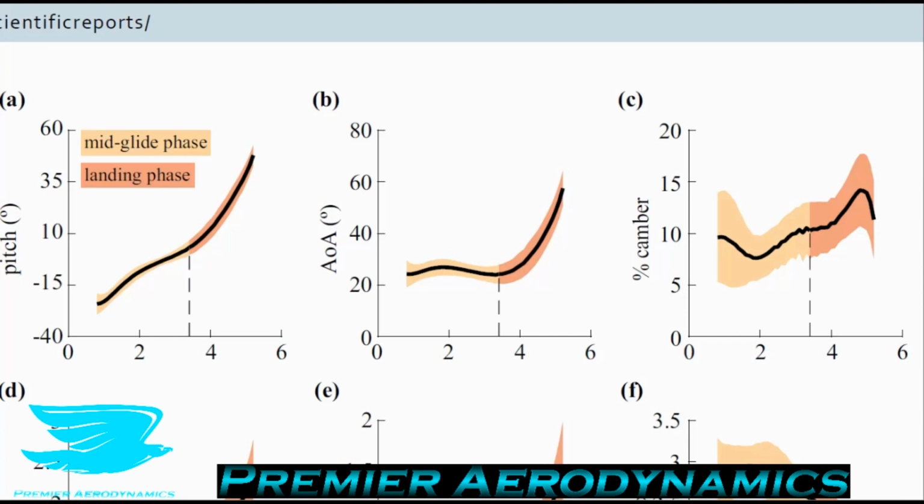It means you can have a smaller planform area, a smaller wing effectively, and you can still get around. We're sort of looking at the lizard in an isolated fashion here where it's just gliding. We have to remember that the lizard has a lot more functions in its life than just gliding around. So having a really big planform, even though that is good for gliding, may not be good for other things such as running around because that's just extra weight, or you have to consume more food because it's bigger, like more cells to reproduce. So the wing could be bigger in theory, but then that would probably hamper it in different ways in life. So having an angle of attack of 25.3 degrees is just an optimal angle of attack for this wing planform that evolution has produced.